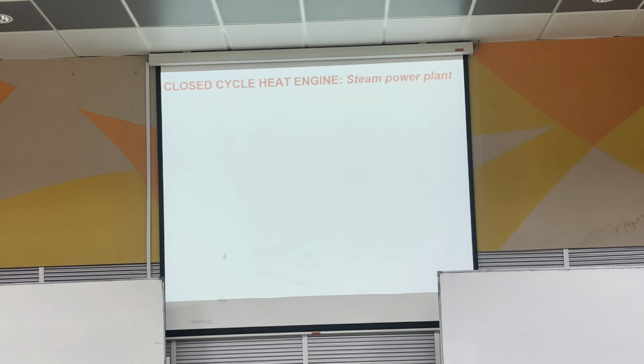And this is the whole basis. So remember in closed system, I said that the general form is Q minus W, because this is what we are expecting. Basically, in general, we are expecting we are throwing in Q in, we are getting work out. That's why the general equation in the closed system is Q minus W. That's the whole reason behind it. And when you expand, you still get work out minus work in minus Q out, right?